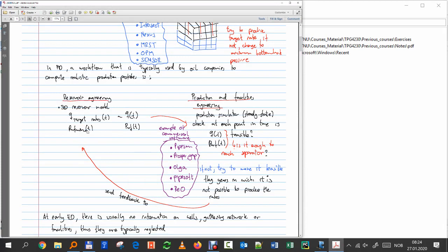And the way the reservoir simulator works, I have to specify these two numbers, right? Target rate that I wish to produce, and then the minimum bottom hole pressure. If I impose this rate and my pressure is still above that pressure, that means that I will be able to produce it. If not, then I have to reduce the rate and simply fix the pressure constant, at a constant pressure.